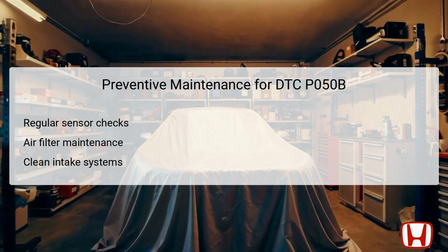Preventive maintenance plays a vital role in minimizing the occurrence of DTC P050B and ensuring smooth engine operation during cold starts. One key preventive measure includes conducting regular checks on critical sensors, such as the ECT and MAF sensors, to catch potential issues before they cause significant trouble.